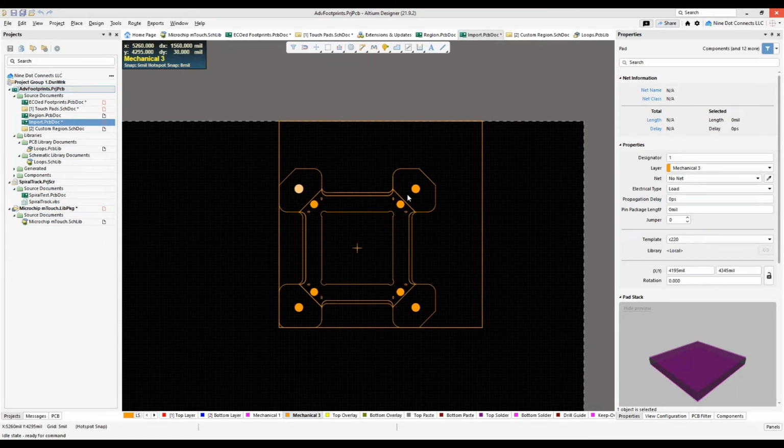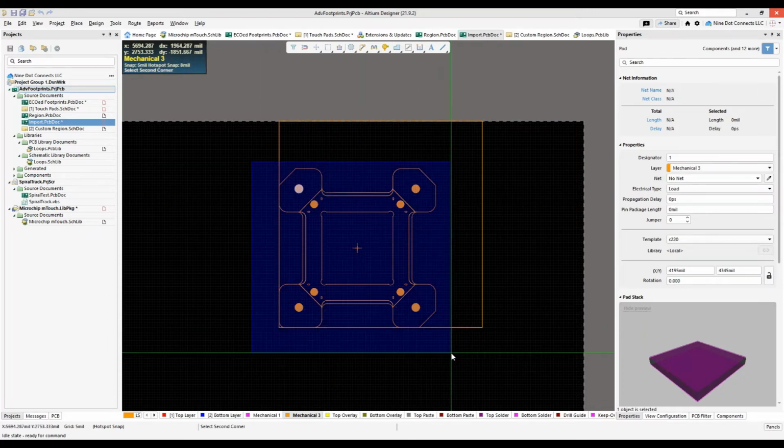Now let me make one side comment to this. In a PCB design, anything can be a part of a union, including a component. However, if you have a component as a part of a union, Altium will not allow you to resize it, because obviously it does not want to change the scale of the component itself. Fortunately, everything you see over here is a primitive, and so I should have no problems resizing this.